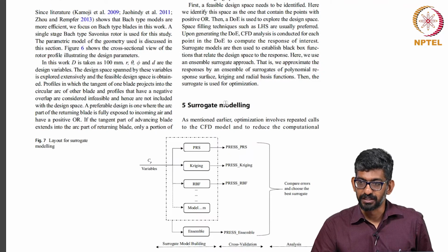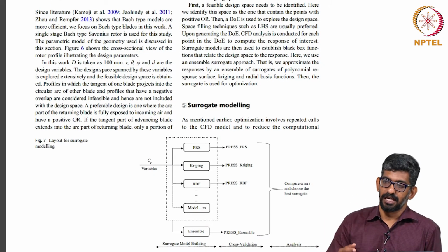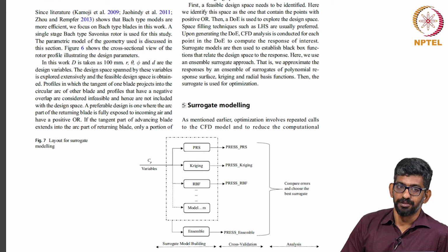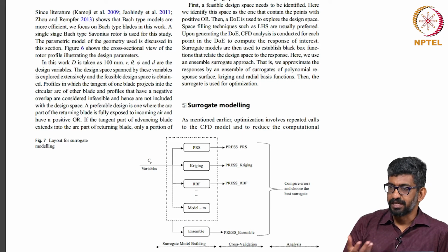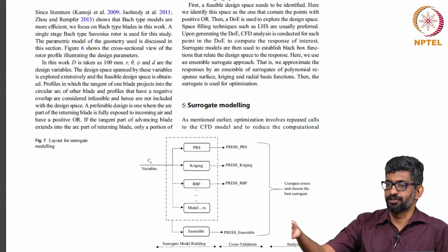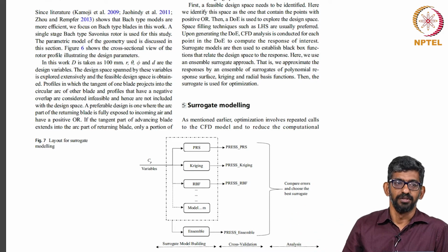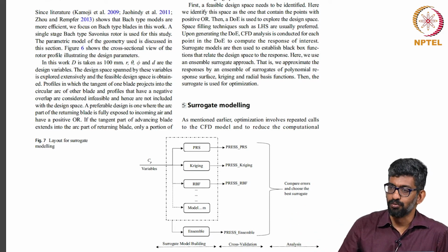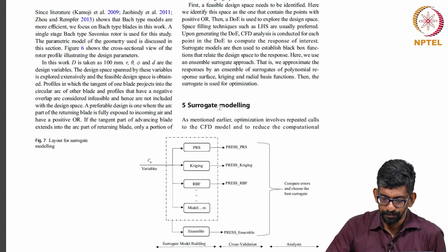And the approach that we are taking is, because this is a high fidelity computer simulation, it takes a few hours, if not a day or so. But again, in an optimization sense, you do not know where you are going to get locked. So, you do not want to directly connect your finite element model to your optimizer. So, we decided to do a metamodel kind of an approach.